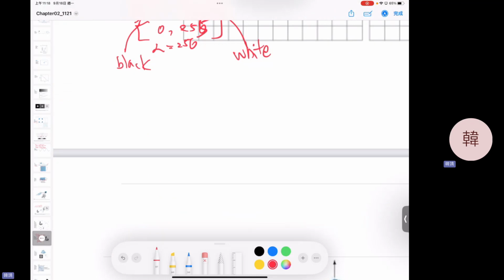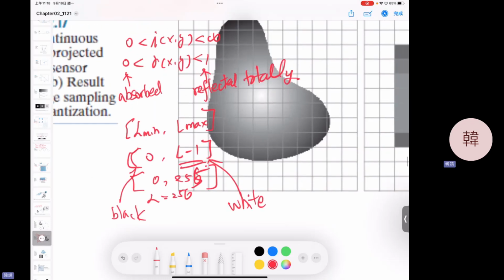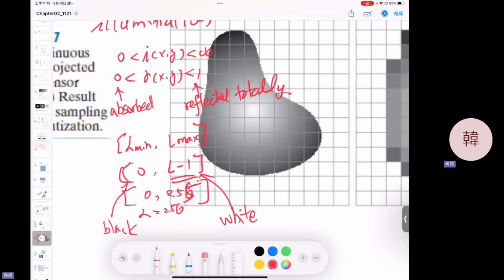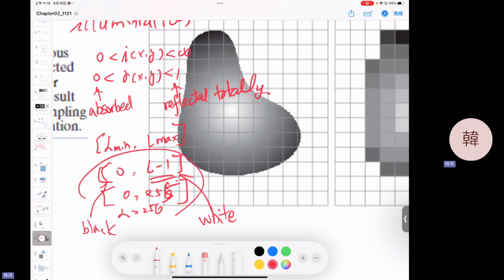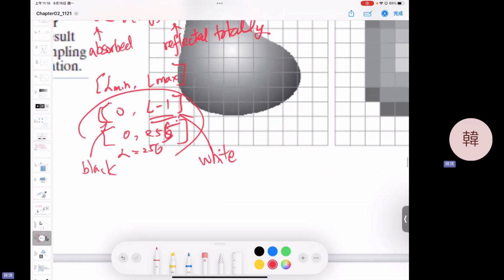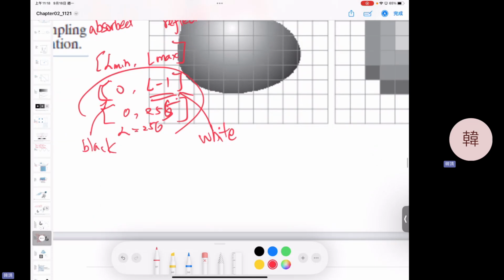So we have this quantized value in digital, in discrete value, and it is not necessarily a linear way to do this. Sometimes you can do a nonlinear quantization. Okay, not necessarily equally spaced to discretize your gray intensity levels. Maybe you want to have some more specific detail in a similar background. You can have more different gray levels.